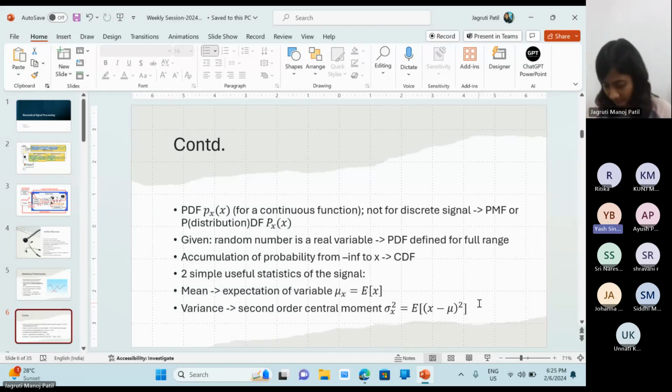It minimizes error in the prediction of any one value in your dataset. Meaning if there is any dataset and we take the mean, then it has the lowest error. Yes. So whenever we do signal processing, unless the mean has some significant value, we subtract the mean from the entire dataset, or we subtract the minimum value as well, so that we don't get maximum errors, so that we are at the baseline, or all of our data is averaged to the same reference point.